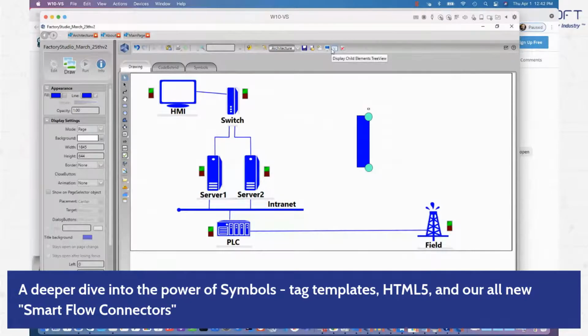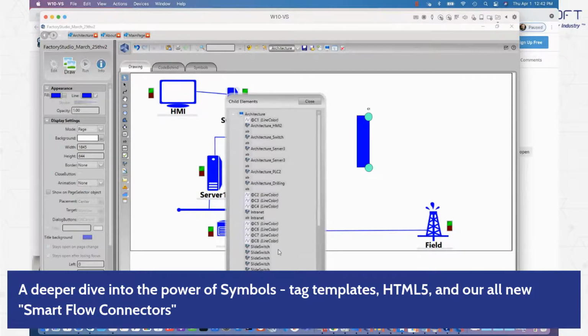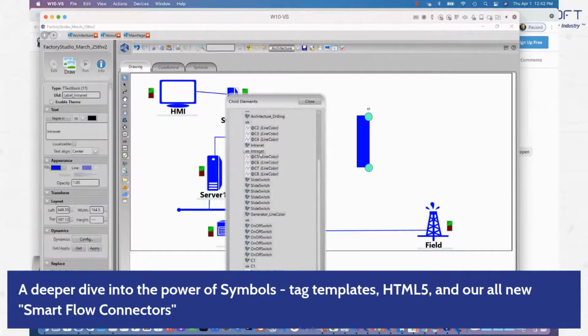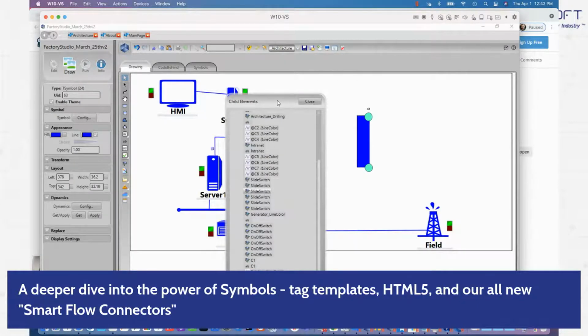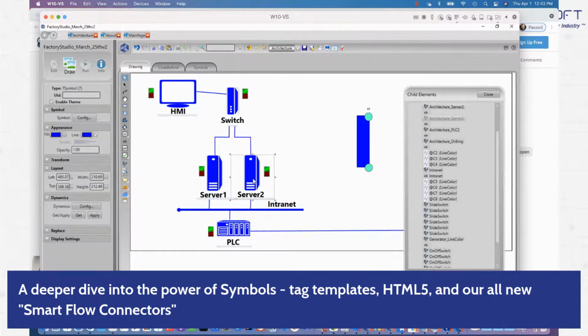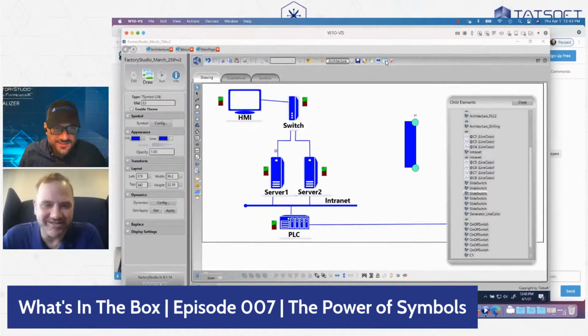Yes, and also a feature that's not new, but since I'm talking about displays, many users never notice, believe it or not, that you have this little icon that opens your screen as a tree view. And you can select elements through here. You can copy and paste dynamic properties. So you can access the elements visually through here or through the tree view as well. It's a little hidden feature that's been here for almost 1 year. It's not even new in 9.0.1, but I know some users didn't know that we discreetly added that feature here.